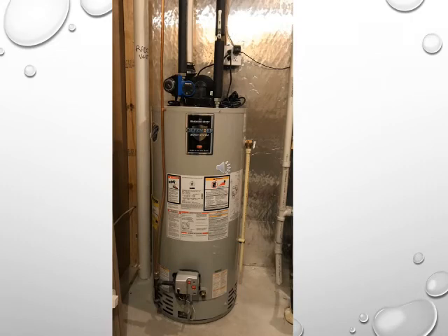And here we have a power vented water heater. We can tell that by the telltale fan that sits on top. This helps vent the gases up through the second clue, which is a plastic vent for condensate. It's a condensing type appliance, so it'll have a condensate drain for the water vapor that builds up. And our topic for right now is this wonderful hot water circulation pump.